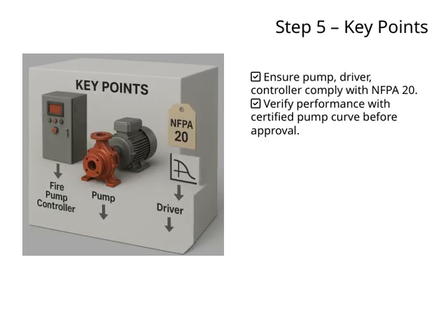All right, moving on to step 5, key points. First, it's crucial to ensure that the pump, driver, and controller all comply with NFPA 20 standards. This compliance guarantees that the system meets safety and performance requirements, which is fundamental for reliable operation. Next, before giving final approval, you need to verify the system's performance using a certified pump curve. This step confirms that the pump will deliver the expected flow and pressure under actual conditions.